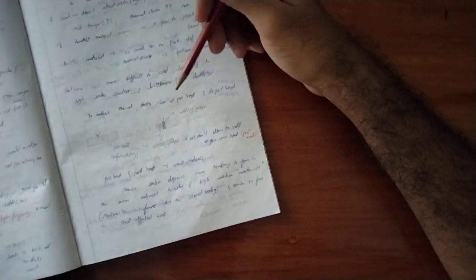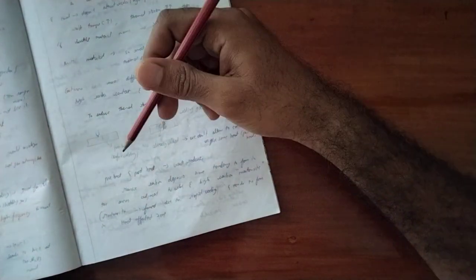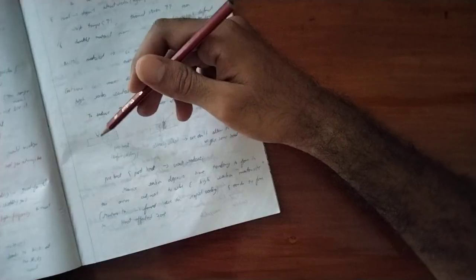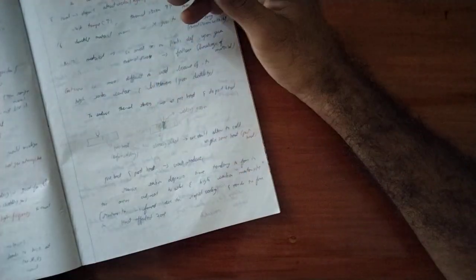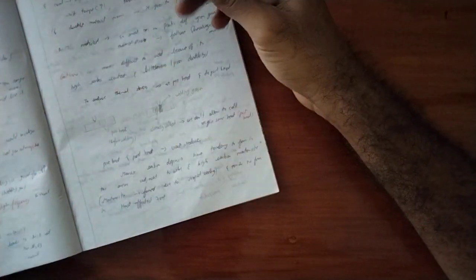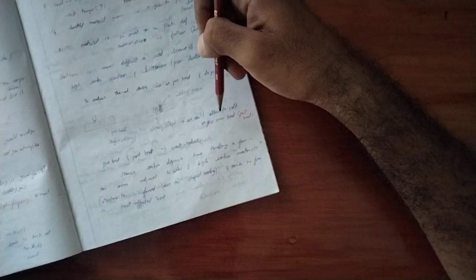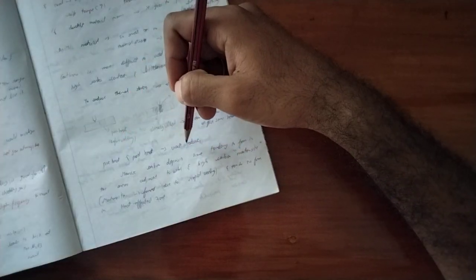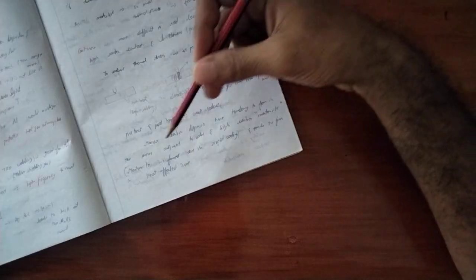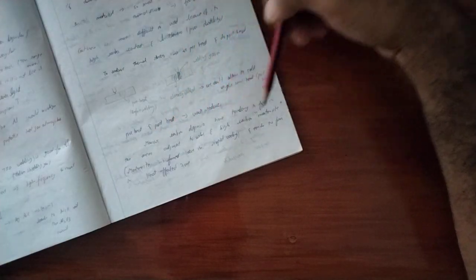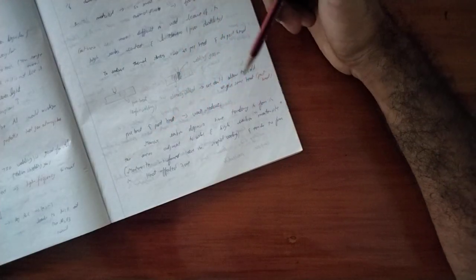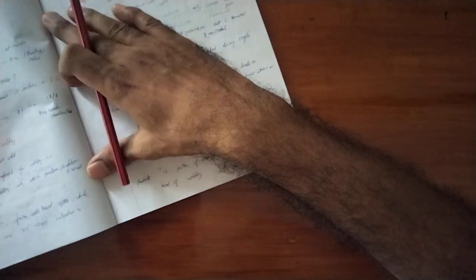To reduce thermal stress, we preheat and post heat it. Okay, preheat is just before welding we heat it. Post heat means after welding we also heat it. Okay, already welded, we don't have to cool it, we post heat it. Preheat, post heat, and cracks reduce definitely. Massive carbon deposits tend to form. So with high carbon, martensite will be formed. So martensite formation due to rapid cooling tends to affect the heat affected zone.